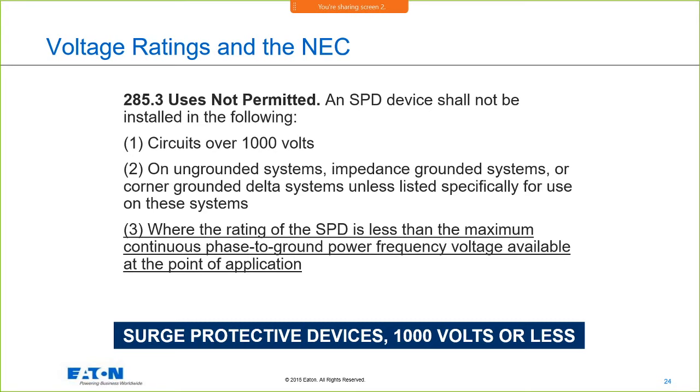The hardest part on most of these is, do you have an extra slot in your panel board to be able to put another breaker to feed a separate surge device? Well, we offer surge built into the standard breaker, so you can serve a 50 amp load and provide surge protection at the same time. That can be a savings to not have to put another panel in.